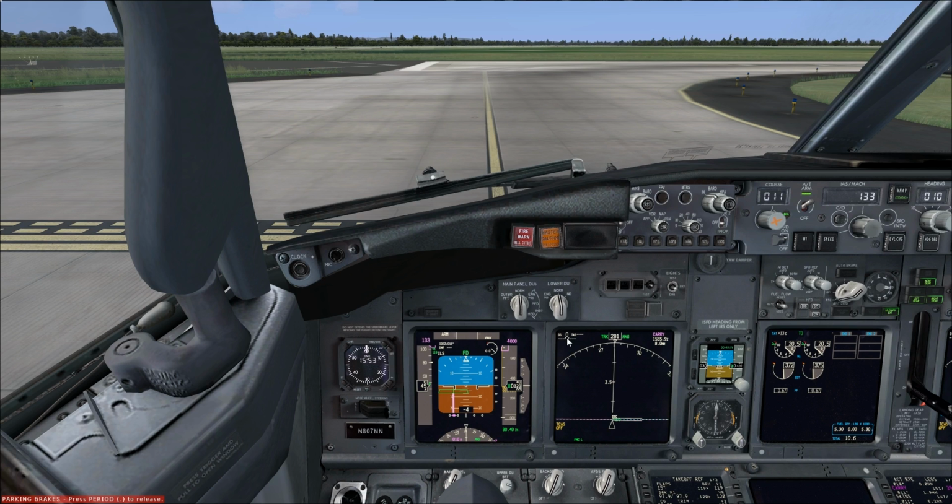And if it's on approach, you'll notice an increase in the rate of descent, and that is caused by the loss of lift associated with the loss of indicated airspeed. Because face it, if you have a loss of indicated airspeed, that means you have a loss of the amount of wind that's flowing over the wing, and naturally you'll have less lift. If you are taking off, the same symptoms would apply, except that the rate of climb would be reduced, and it may even turn into a descent if you're not careful.